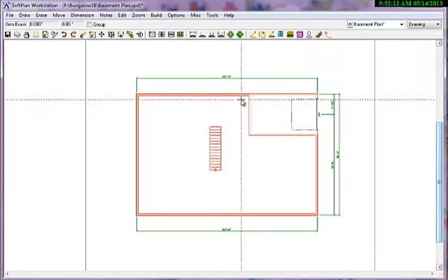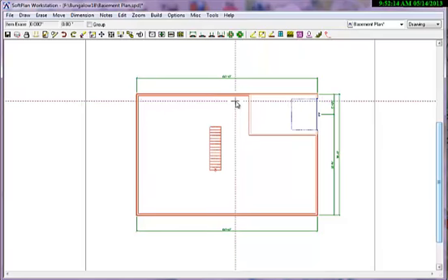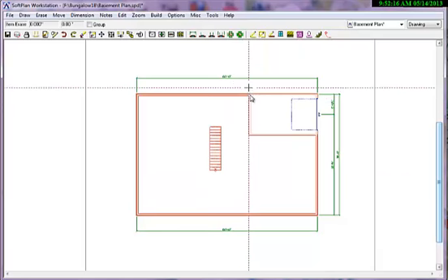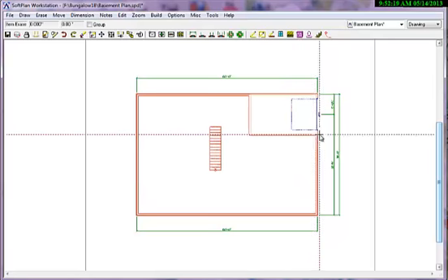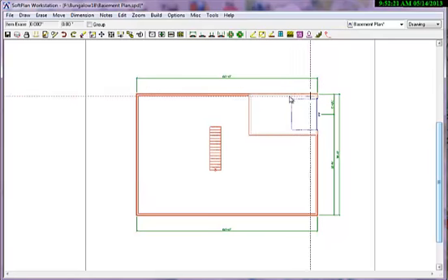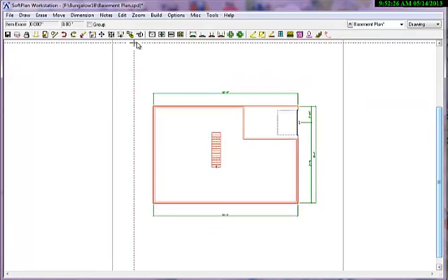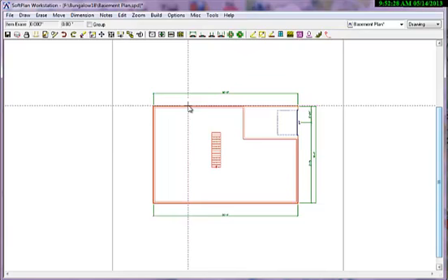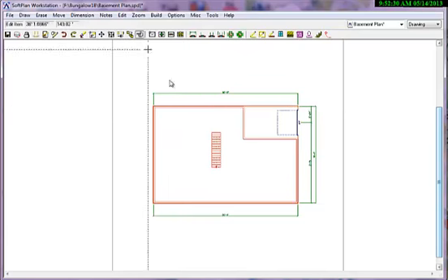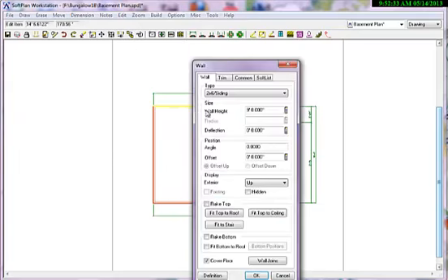Okay, now make sure that before you start to do this, back in your first floor plan, you created a garage with garage walls. Okay, now what I'm going to do is just double check that my wall heights are the same as what you're likely using. So I'm going to go to Edit, I'm going to click on the wall, and mine are 9 feet high walls. I had just selected that in the floor plan. You may have 8-foot high walls. I'm going to change mine just because most of you have probably got 8-foot high walls.